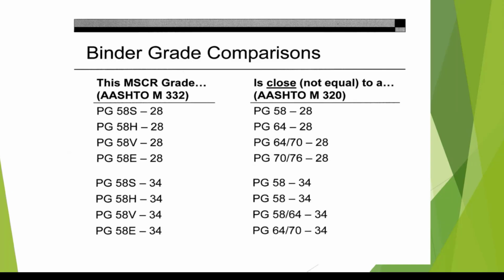So as you go up the line, the minus number should, you'll see that in a second, should stay mostly in North Dakota at the minus 34, because that's the single low pavement temperature and air temperature at the surface of that pavement that's going to dictate the susceptibility to thermal cracking in our environment.